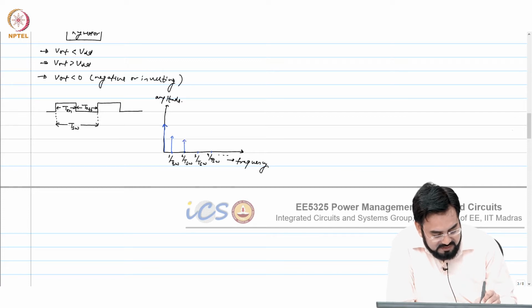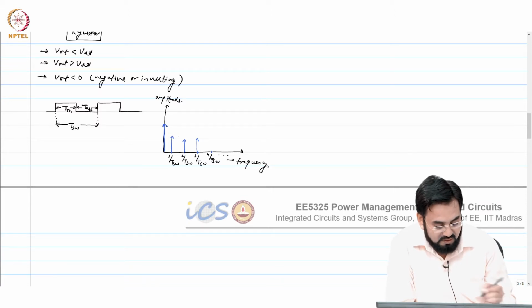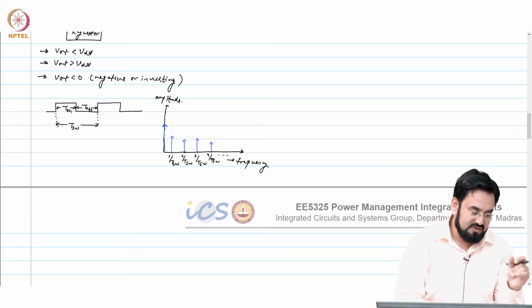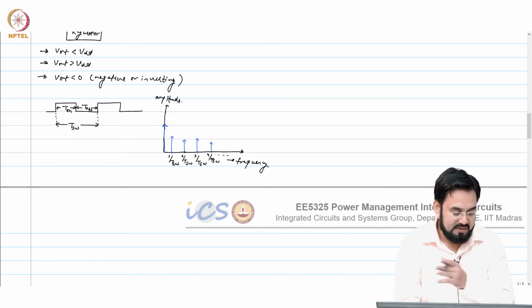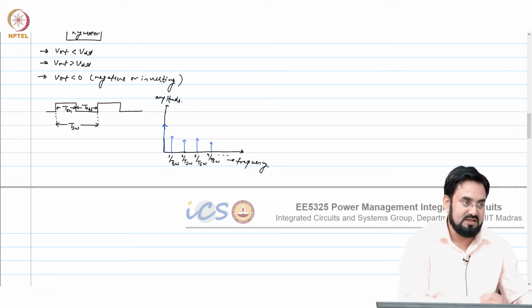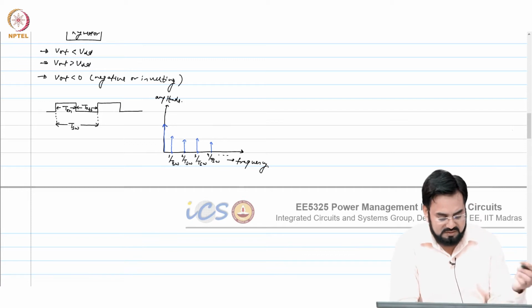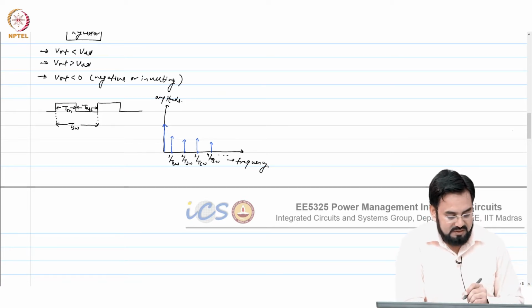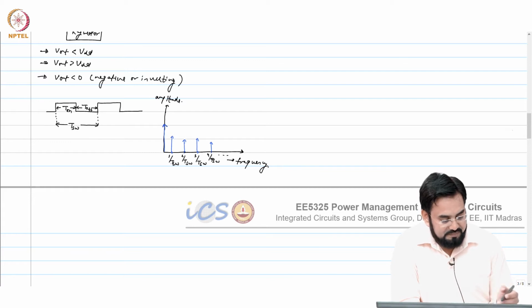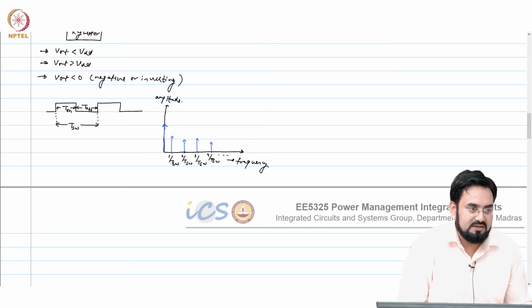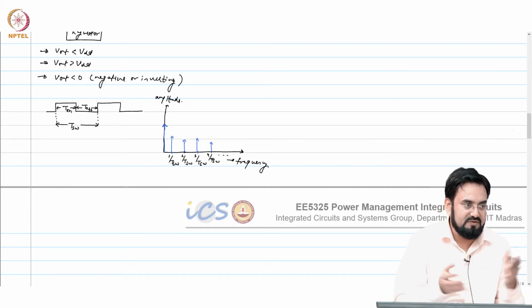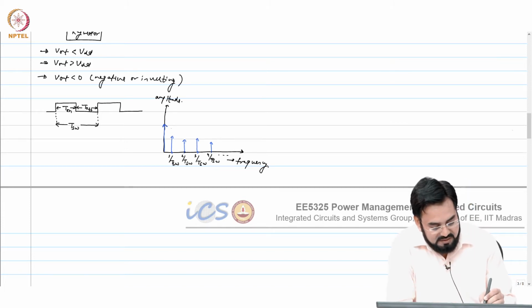So it may be like this. In fact, some of them might be more; if you look at even harmonics, it's not necessary that it will keep decreasing, but it depends on your duty cycle actually. So the expression is not straightforward when you take the Fourier transform or the Fourier series of a triangular signal or any other. And if it's a perfect square wave, then it will have only odd components, but if its duty cycle is not uniform, then it will have both odd and even.